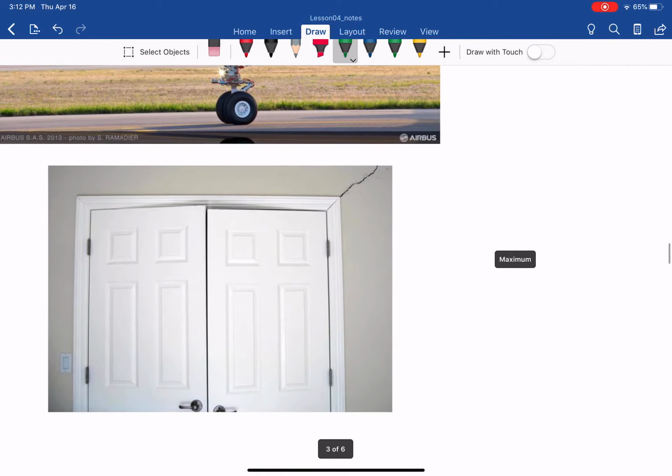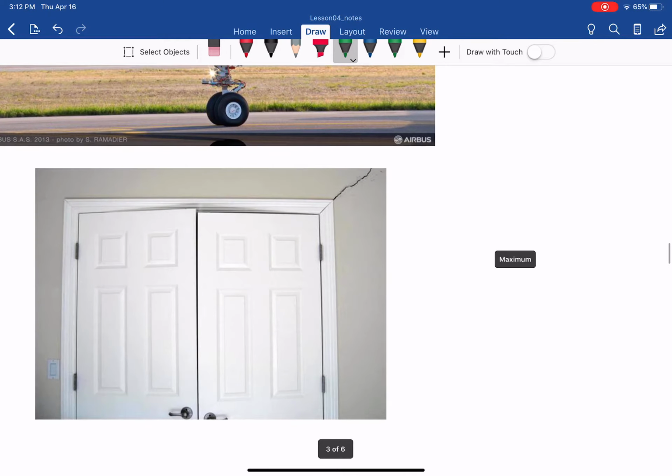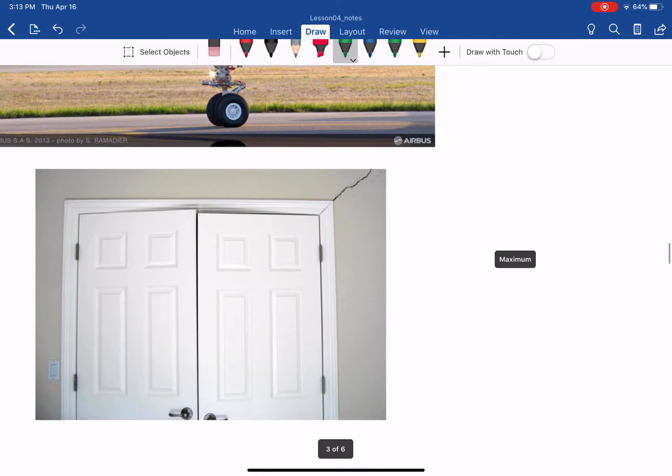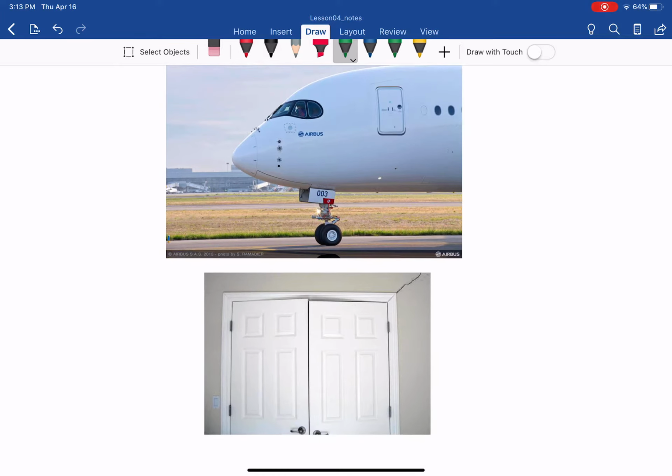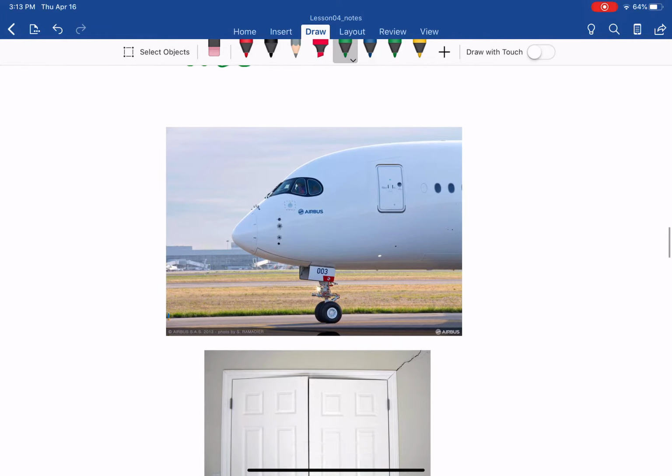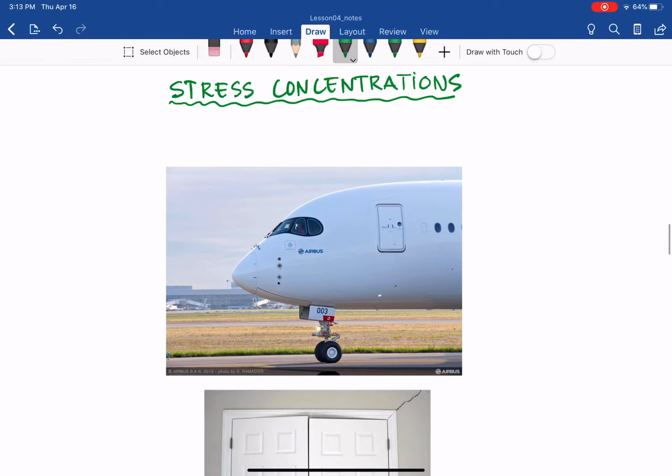And with the door, as you can see here, the crack tends to go through the corner of the door or at the windows, and that is due to the stress also tending to concentrate more on your change in geometry or discontinuity of the material, in this case the empty space for the door, and then the stucco or CMU in there, the cement unit in there. So from that, let me define that, and then we go into detail.